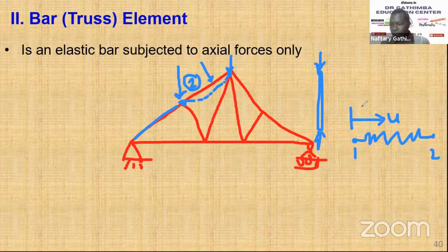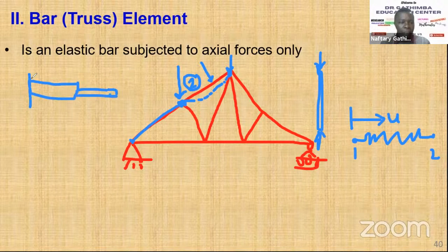The first step, once you discretize, you break down. So once you specify the nodes, they will usually come at the intersection of joints, intersection of different members, or the change of geometry. For example, if you have a bar element composed of two different member sections, and maybe it's fixed on this edge, it's logical to assume that node 1 will be here. Here at the change of geometry, you have node 2, and of course at the edge here you have node 3.